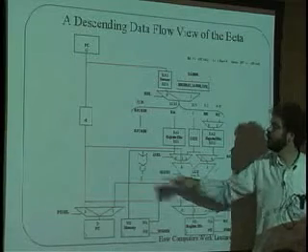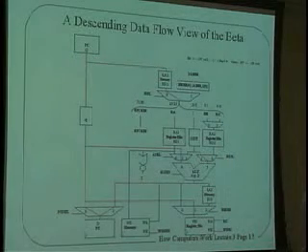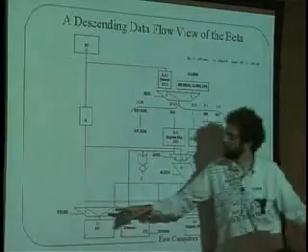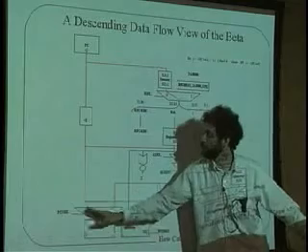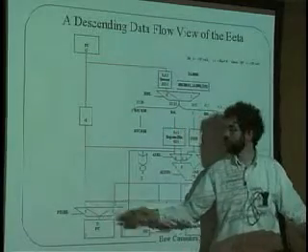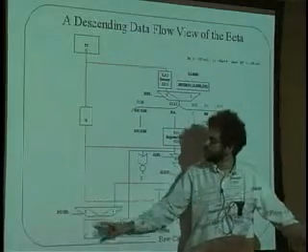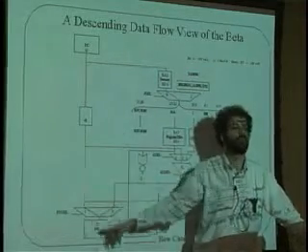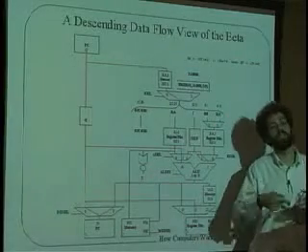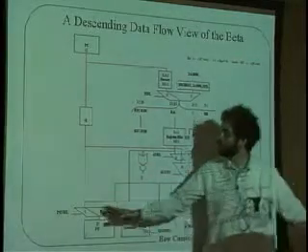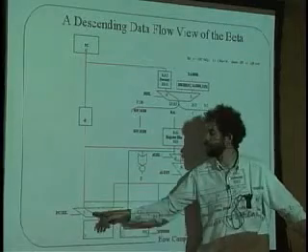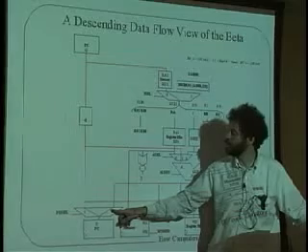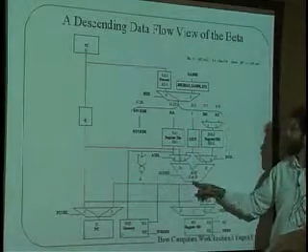And whether or not it's 0 will then control, through the same control logic that looks at the opcode, whether or not PCSEL gets set to 0 or to 1. If PCSEL is set to 0, then the PC will be loaded with what? With PC plus 1. And we'll just go forward to the next instruction. We will not take the branch. If, on the other hand, PCSEL is set this way, and that's why both of these are red here, if we choose this path, then the PC will be loaded with whatever pops out of the ALU.